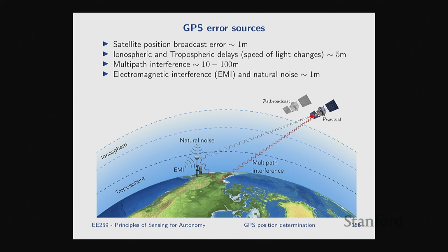And then the actual pseudo range that you find is the sum of the two pieces of the multi-bounce. Or it can be more than two, actually. You can have multi-bounce that is reflected 3 or 4 times. And that completely messes up your localization, because the underlying assumption in the GPS localization is the time of flight is in a direct line of sight. That can introduce up to 100 meters. If you ever use your GPS in downtown San Francisco, it's almost useless. I always get lost, and that's multipath, because you get hundreds of meters of inaccuracy.